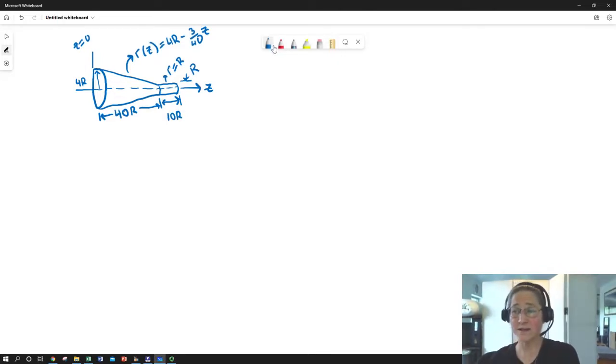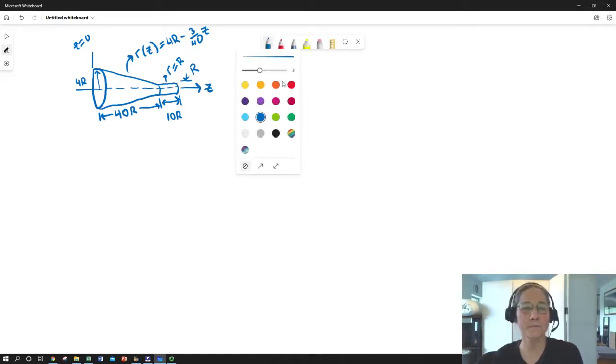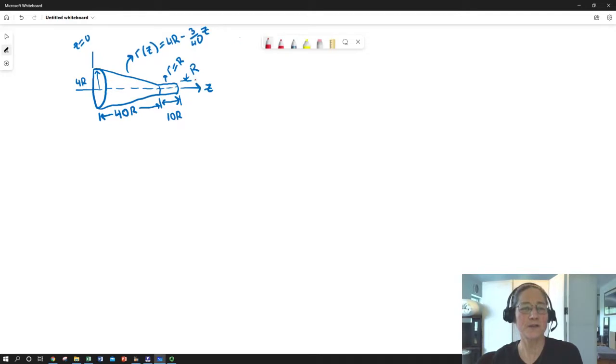Otherwise, we would treat this problem of finding twist rate and angle of twist at any given point along the shaft exactly the same way that we would in a straight constant radius stepped shaft. The first thing we need to do: right now, there's no angle of twist and no stress and no strain because there are no applied loads. So let's start out by applying some loads.